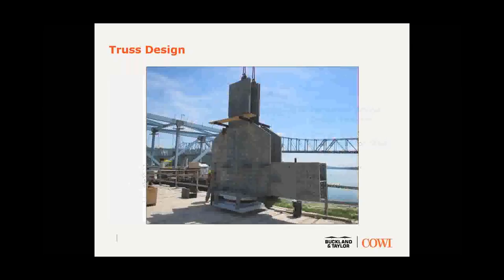One of the joints shown of the truss node is at a bearing, so it's one of the larger joints. You can see a person standing there and get an idea of the size of the truss node. All of the truss members themselves are welded H sections. You can see a bottom chord H section and a king post coming up from the gusset plate there.